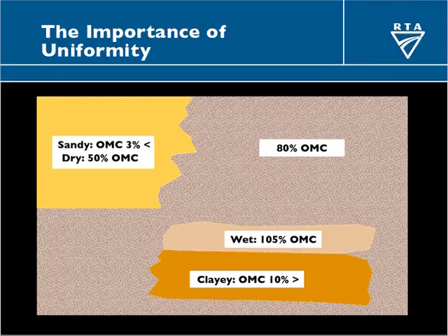So instead of having a very simple uniform task, we've now got a mess. Some bits not compacted because they're different and too dry. Some bits not compacted because they're the same but too wet. Others, it's a different material, and maybe your compaction routine will work, or maybe it will not. You may be lucky, but in the long run, this will give you trouble.